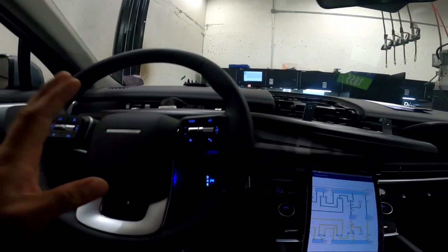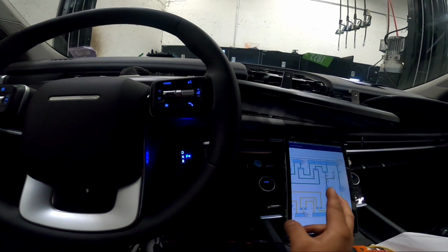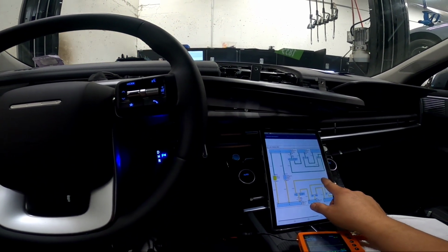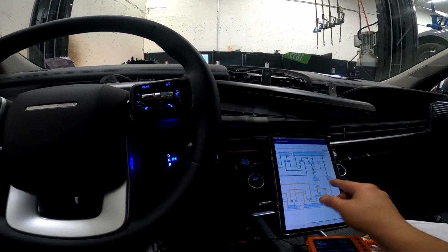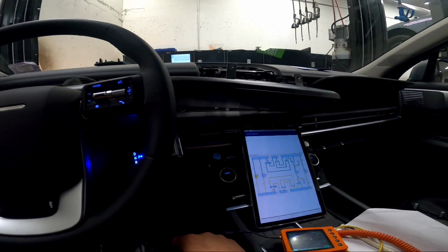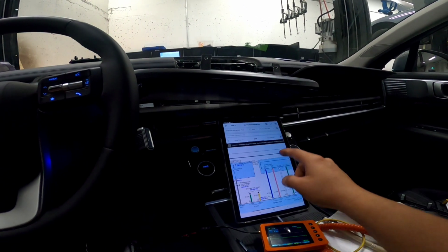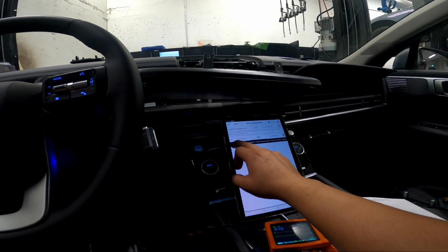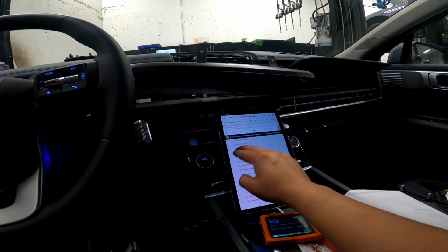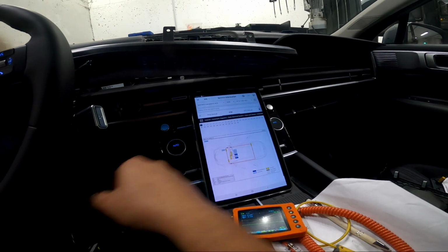So I'm gonna turn off our vehicle first. Let's measure the resistance there. We got two terminating resistances, CCU, right? And the cluster, we should get 60 ohms there. So let's double check that. Data link, just to make sure that those two modules have the terminating resistor.